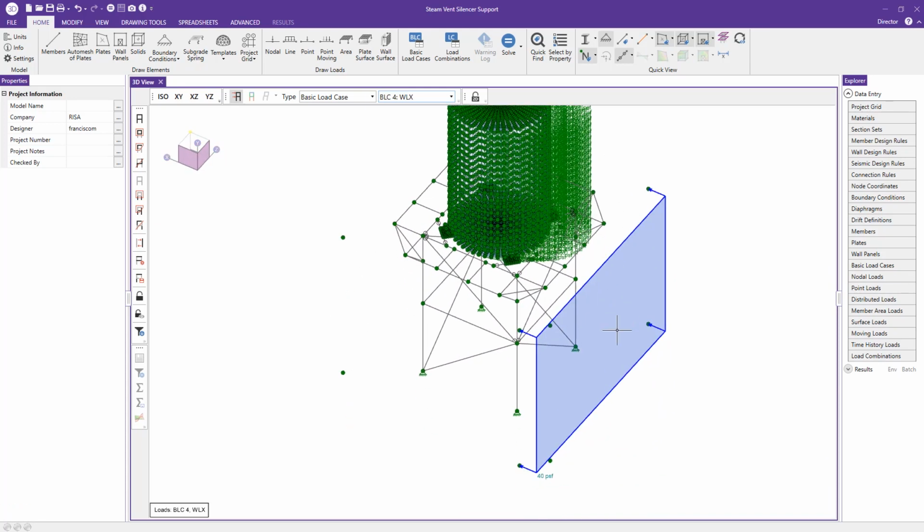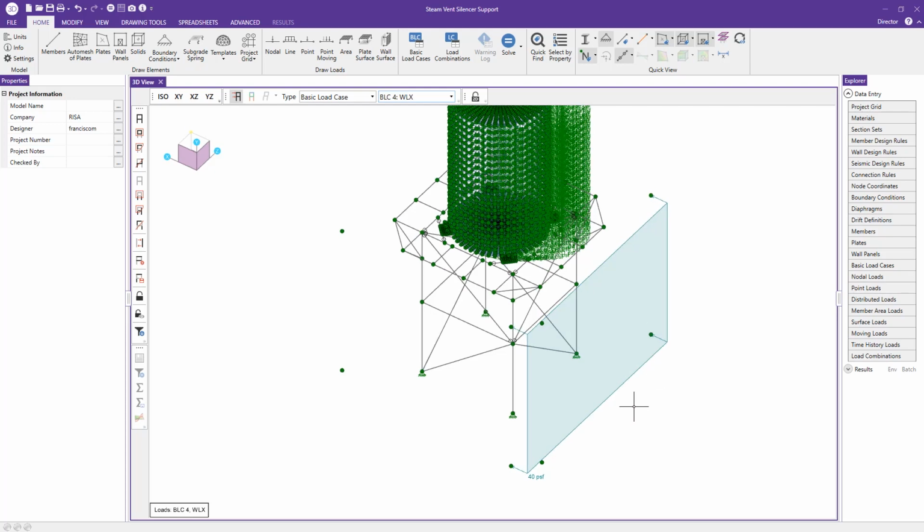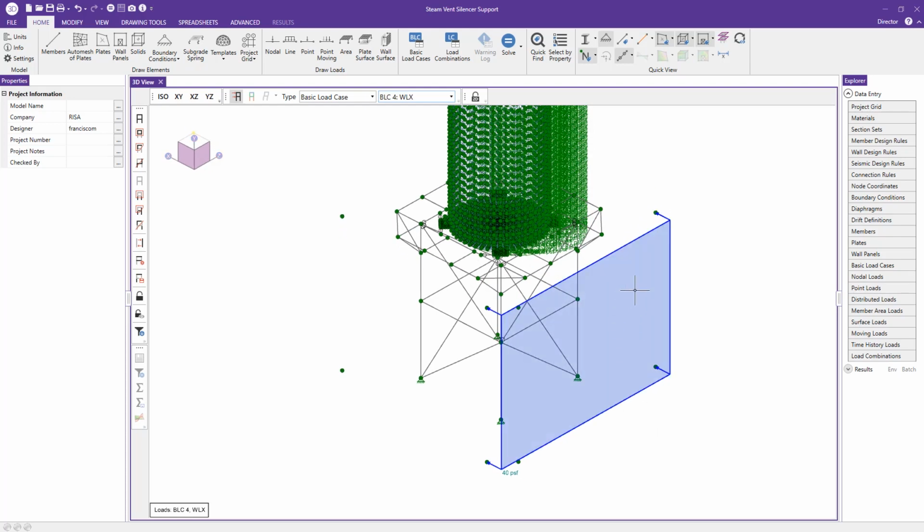Okay, so the first thing we'll touch on is these open area wind loads. What this is going to connect back to is the Chapter 29 ASCE 7 wind loads that we were taking a look at from our slides. If you remember, we calculated a pressure essentially from that equation. Once we've calculated that pressure, we can utilize RISA-3D's smart capabilities to apply this wind load as an open structure wind load. I'll show you how to do that in just a second.